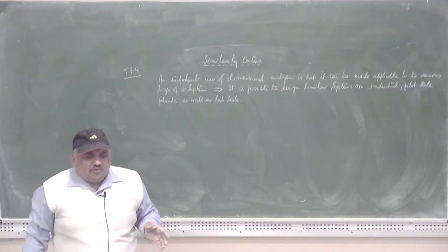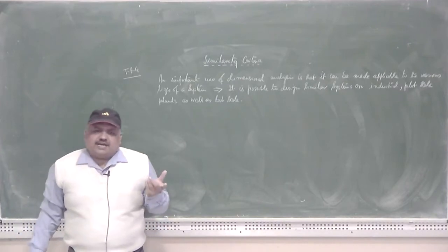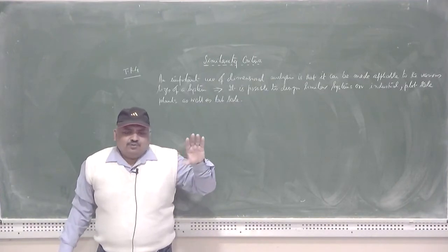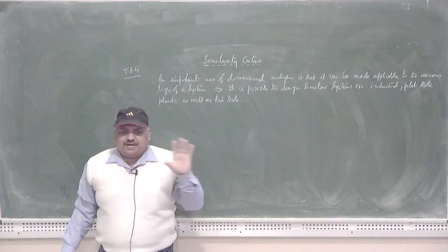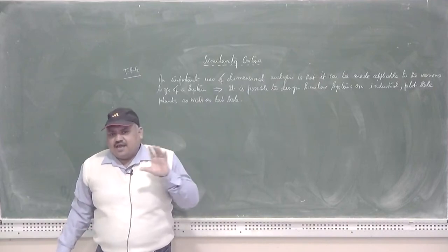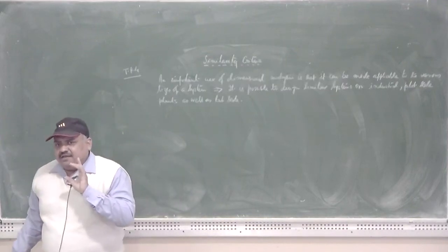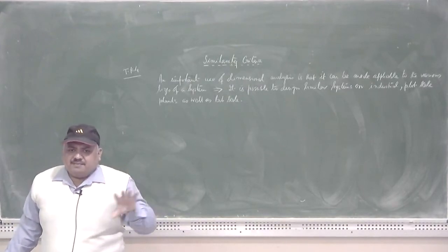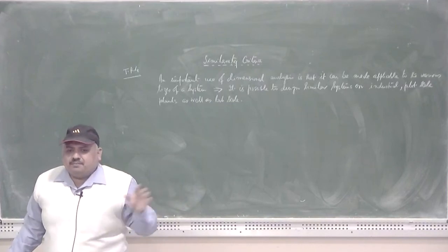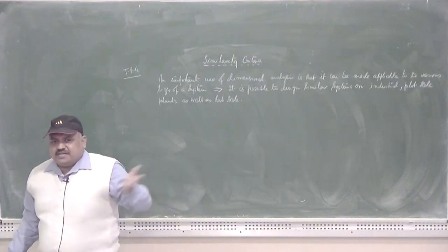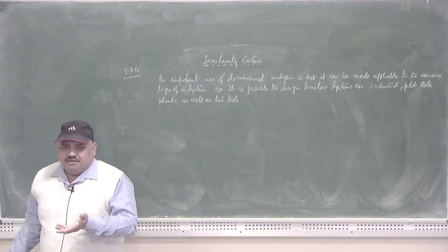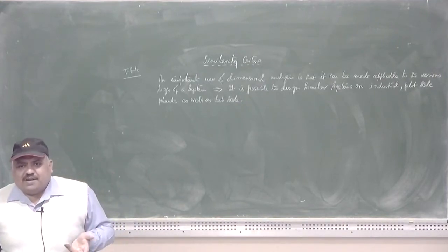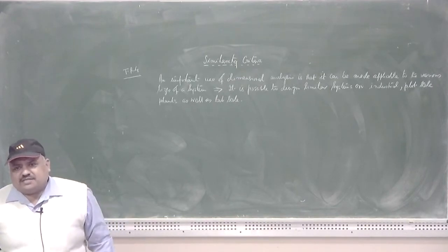Keeping in view that the blast furnace is cylindrical in nature, if you are designing two systems on different scales, one on the industrial scale, another on a pilot scale, it is necessary to emphasize that the length by diameter ratio must be the same in both cases, failing which any data that you have obtained on the prototype level may not be simulated on an industrial scale.